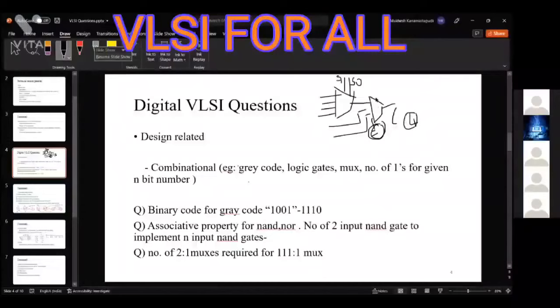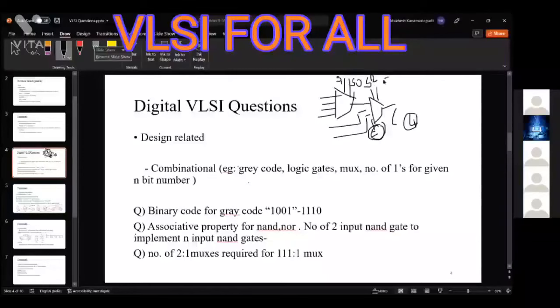For 6 inputs we have to take 3 selection lines, maximum 3. So by taking 2 4 by 1 muxes, we give 6 inputs. By taking 2 as selection lines for the 2 4 by 1 muxes, one must be taken as an enable input to both the 4 by 1 muxes. Yes, one select line will be common for both. Correct.